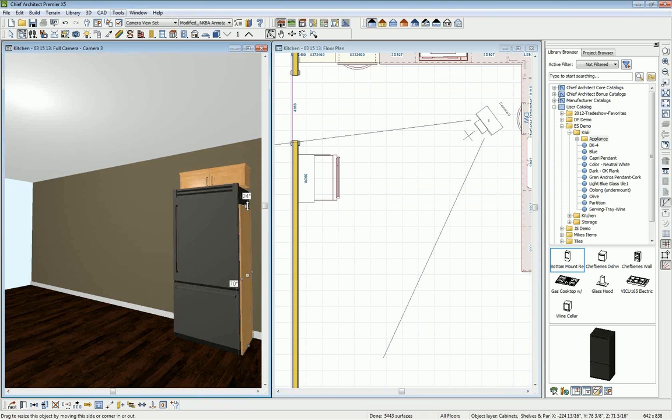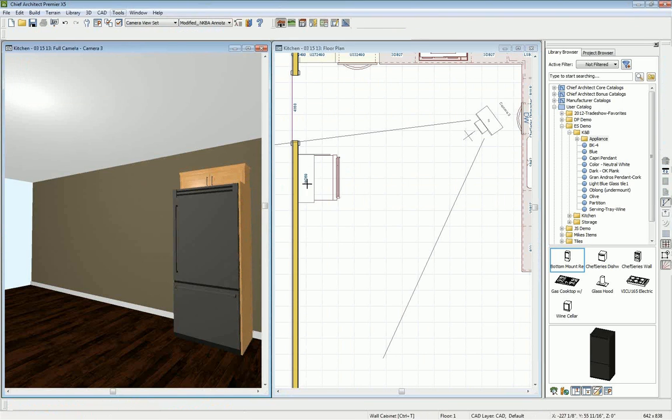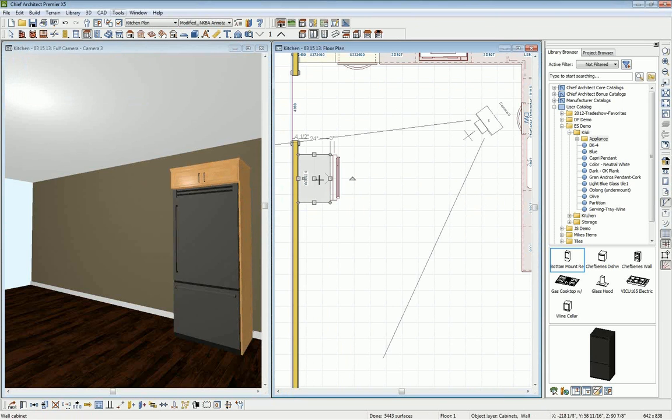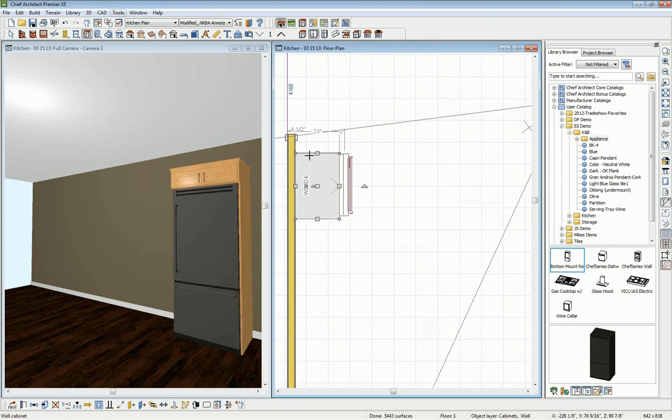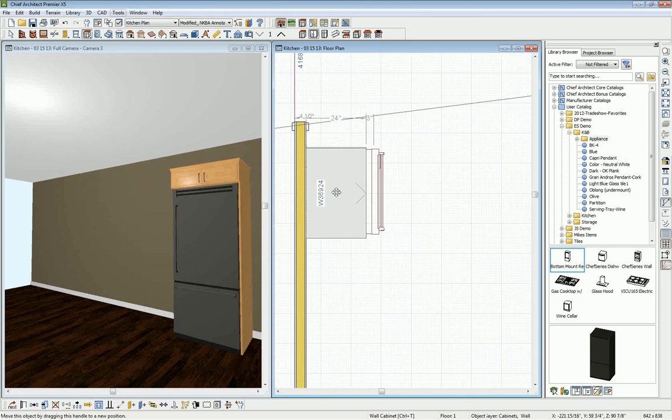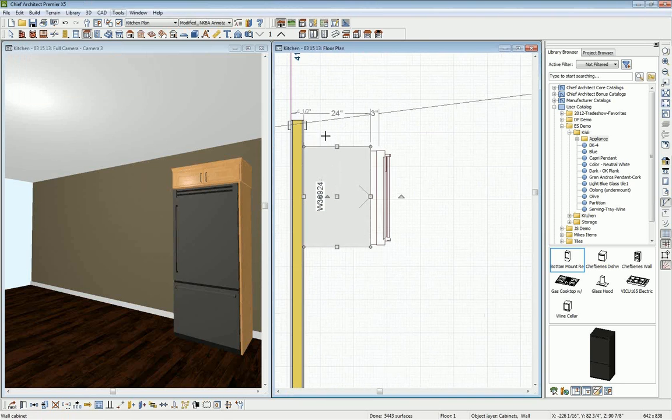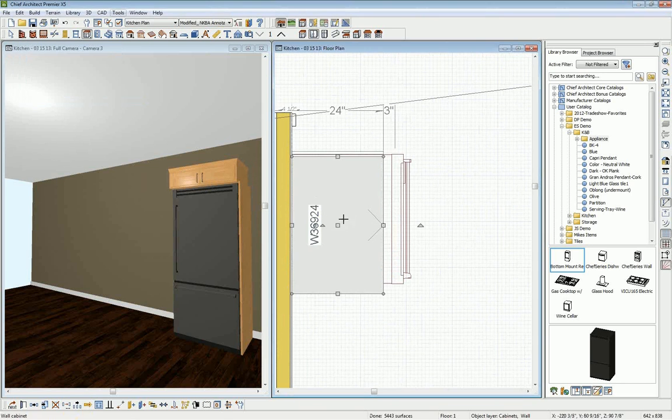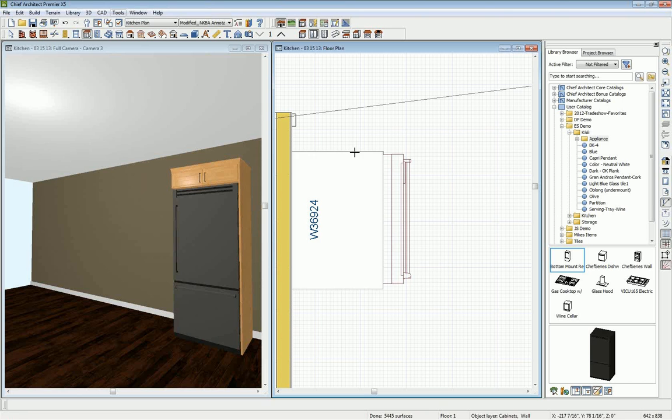And in our 3D view, let's work with our dimension here. We're just going to bump that up. So that's another reason to have your 3D view open as well. It's great to manipulate your dimensioning. So I'm just going to move that over here. I'm going to just zoom down here. We have a quick tool. It's called point to point. So I'm going to select my wall cabinet, click my point to point move tool from my editing toolbar at the bottom here, and then just click on each corner to get that moved. And let's see, I can also hold down my control key to free up any snapping that might happen there. Alright, so we have that side done.